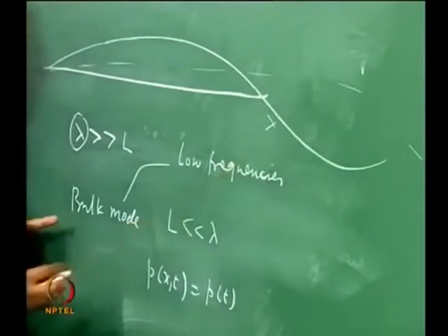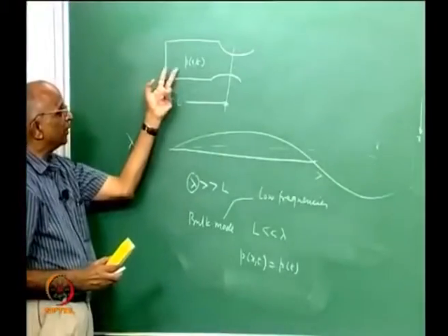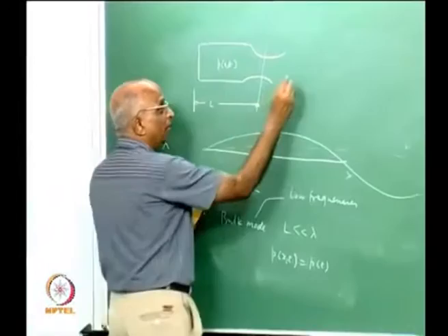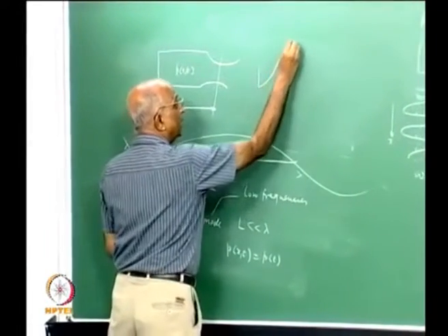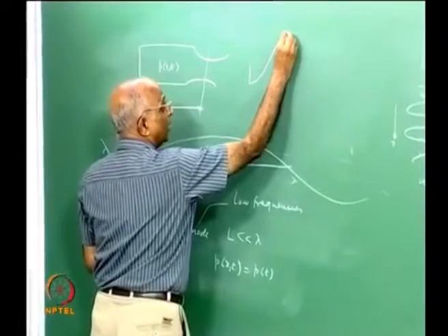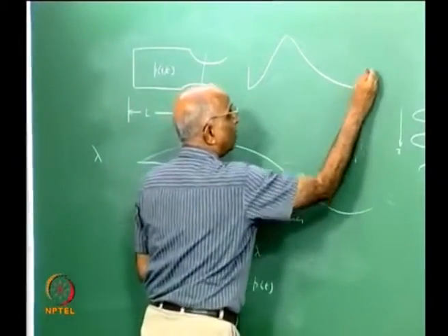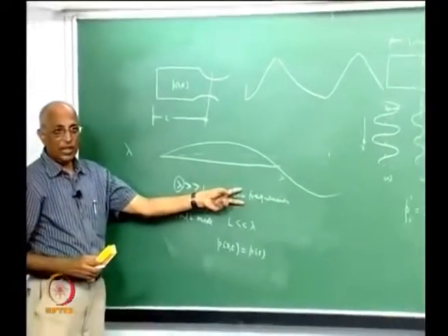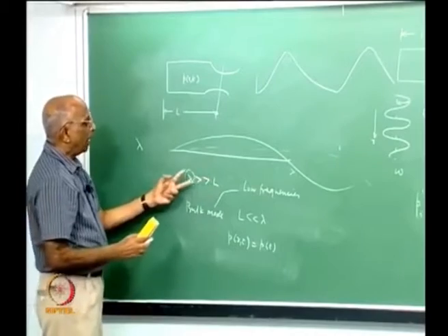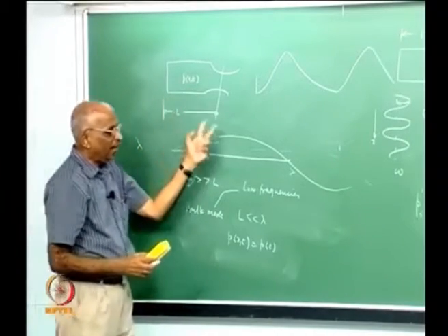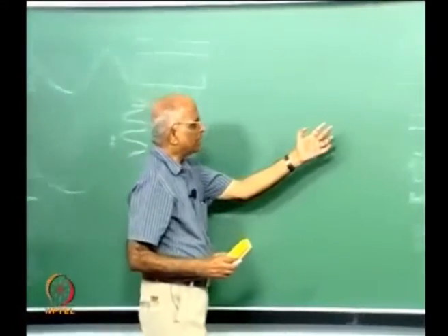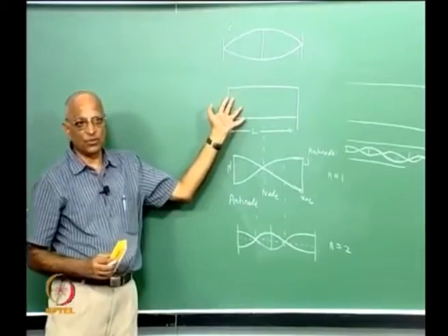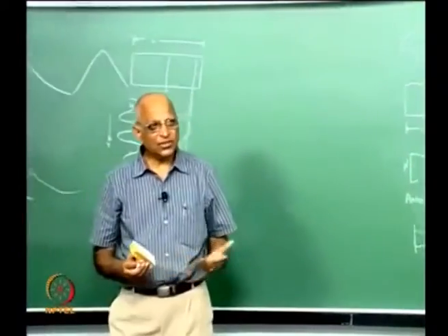Therefore, whatever we studied for bulk mode of oscillations, coming from the injector or from a solid propellant from the response of the surface, giving you the oscillation wherein the pressure came down, again it went up, it went off, and then again it came down like this, again it went off, again it came down. These have to be essentially at low frequencies. Therefore, L star oscillations which we studied yesterday are essentially low frequency oscillations, and the wave mode of oscillations must essentially be at higher frequencies. I think this part must be clear to each one of us. Okay. Let us now go forward.